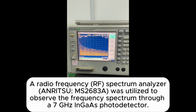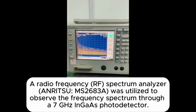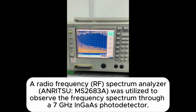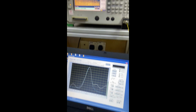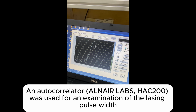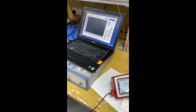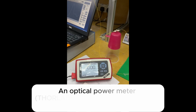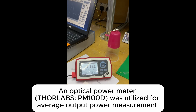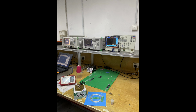A radio frequency spectrum analyzer was utilized to observe the frequency spectrum through a 7 GHz indium gallium arsenide photodetector. An autocorrelator was used for examination of the lasing pulse width. Finally, the output power meter was utilized for average output power measurement of the generated pulses.